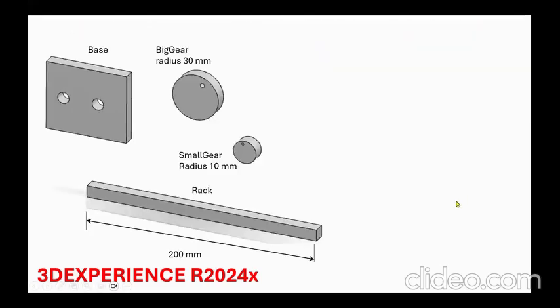I really don't need any dimensions in this problem, except that since I want to check some physics, I will assume that the radius of this big gear is 30 millimeters and the radius of the small gear is 10. And why I do that is because later on I want to specify, for example, the small gear's RPM to be 180, which is incidentally 18.85 rad per second.